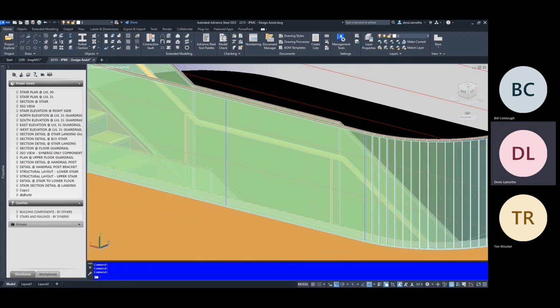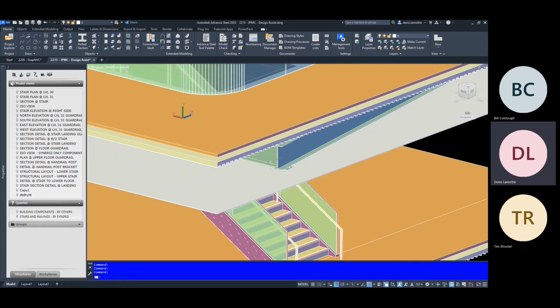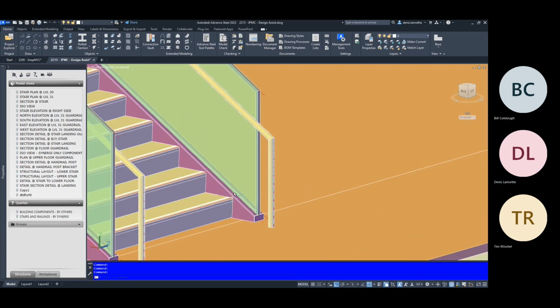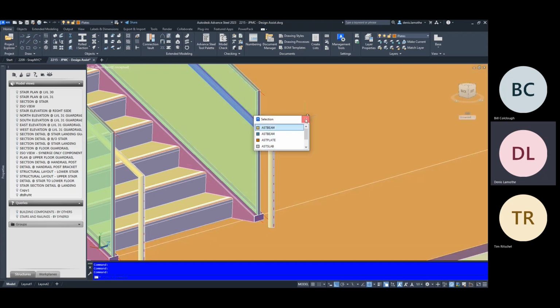At the bottom of the stair, however, it doesn't need to be horizontal. But it does need to extend past the first nosing, or last, I guess, depending on your direction of travel. The handrail termination should be equal to a tread width after the first nosing line. So if your tread widths are say 11 inches nosing to nosing, then the handrail here should terminate 11 inches past this nosing at minimum.